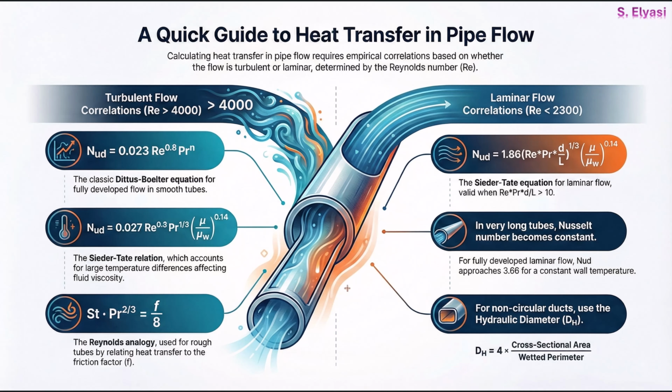Calculating heat transfer in pipe flow. So this is your quick breakdown of the key empirical correlations engineers use to figure out thermal performance inside pipes. And you gotta know, all of these calculations really depend on the flow's Reynolds number, or Re.